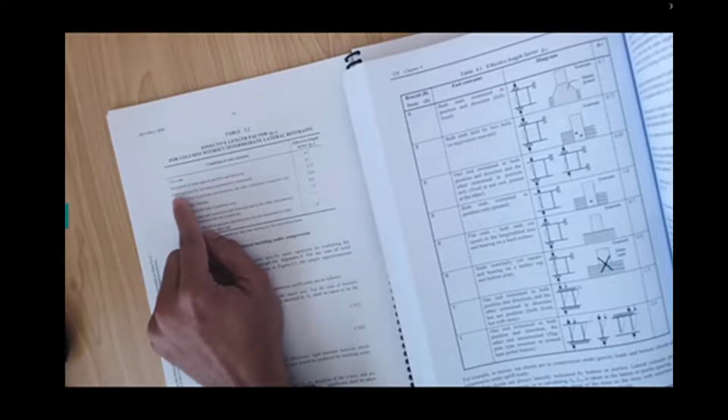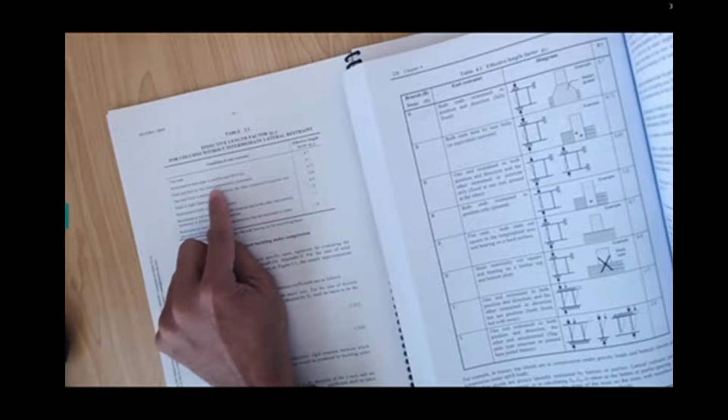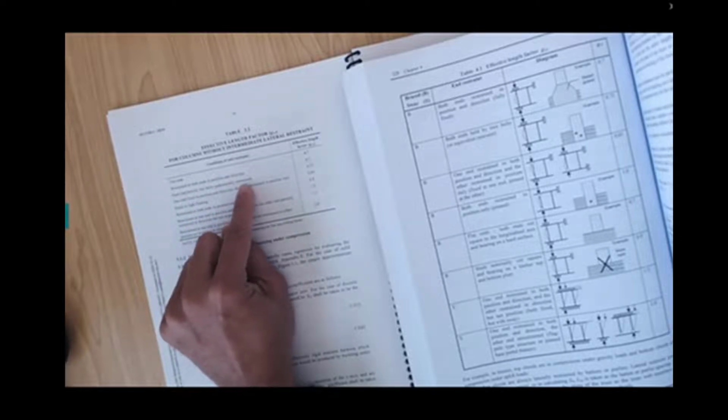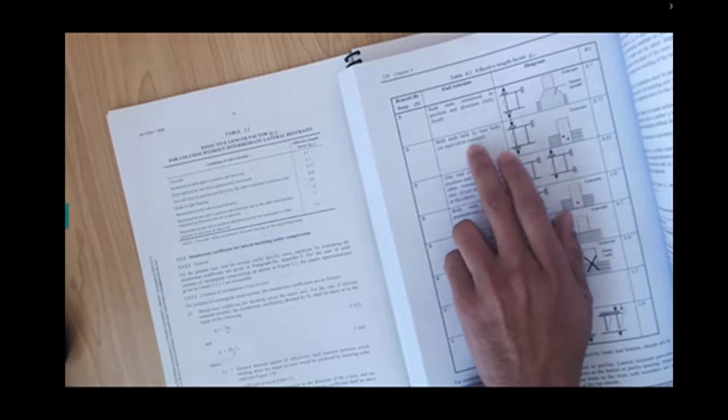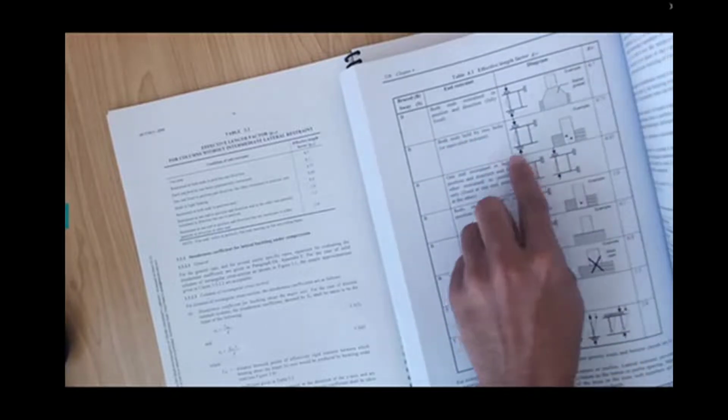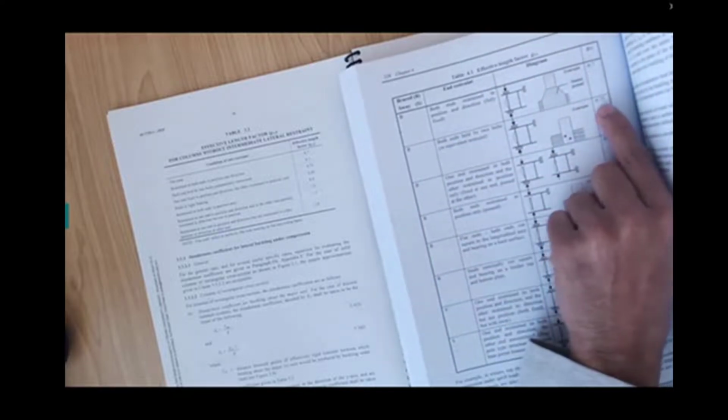Now, I hope you understand these two, which is your fixed end, and this is part of brace columns, by the way. Now, the third case is each end held by two bolts, substantially restrained. You remember that you have this bolt in the lectures. We have 0.75, kind of a pin. So you have these two bolts. So both ends held by two bolts, equivalent restraint. So it's kind of fixed, but this bolt sometimes has slight rotations. It's not showing here, but it is not rigid, it might have very slight rotation. Therefore it's just putting a little bit extra, 0.75.